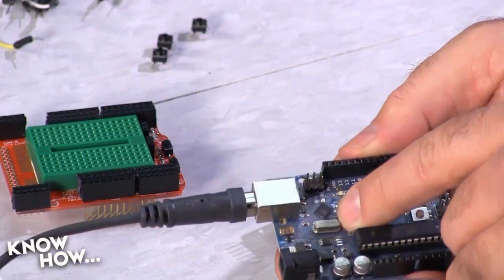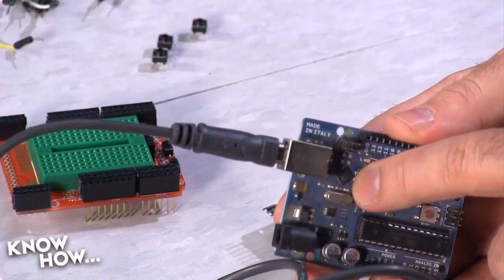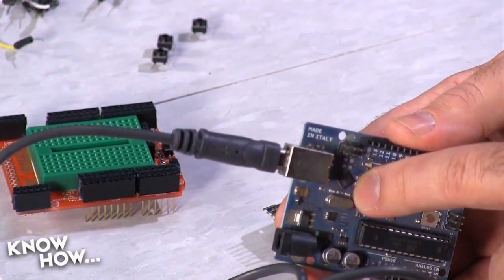That little metal canister right there, that is a 16 megahertz clock, and it's 16 megahertz-ish. It's not very precise. It's quartz, right? It's a quartz crystal. They figured out that when you compress it, it's going to vibrate a certain number of times per second, and that's what gives you your timing. Exactly. But it's not very precise. Right. And so if you rely on that to count the time, it'll be slow or fast, or it'll change over time. They're not very well heat compensated.